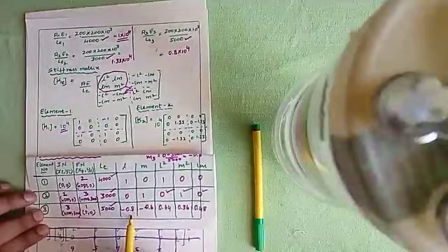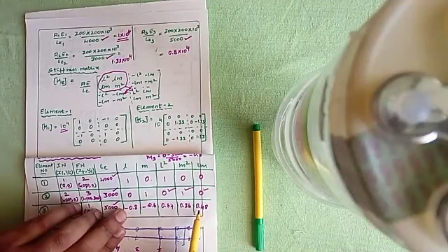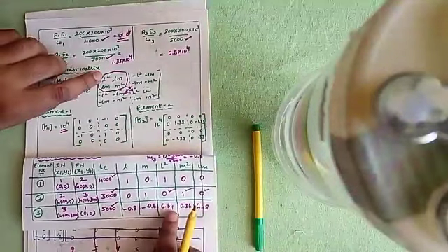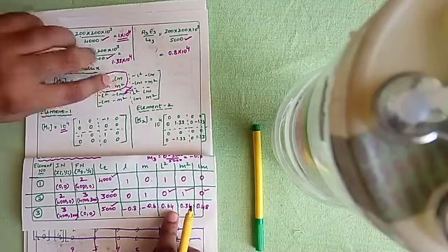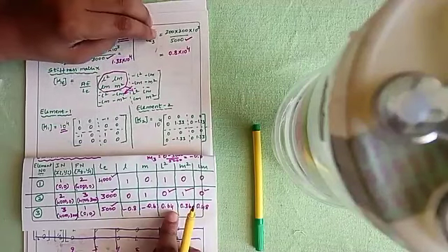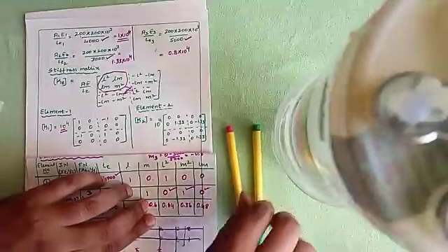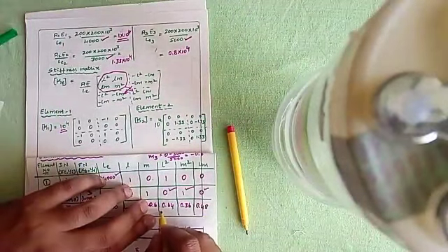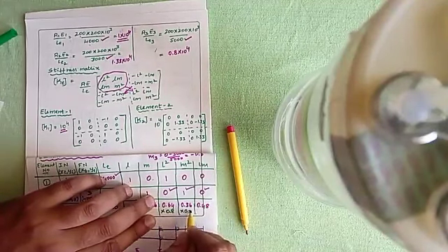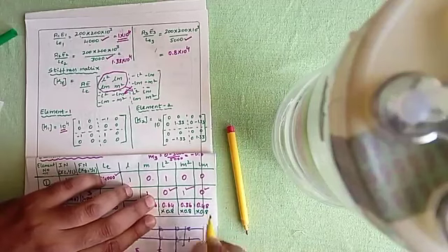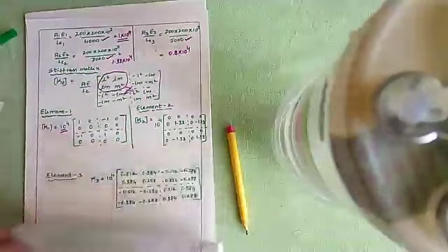Now let us come to element number 3. L² is 0.64, M² is 0.36, and LM is 0.48. So L² is 0.64, LM is 0.48, and here also you're going to get 0.48, and M² is 0.36. When you multiply A3E3/L3, you're going to get 0.8 × 10⁴. Now I'm going to multiply this L² with 0.8 inside the stiffness values, and 0.36 also with 0.8, and 0.48 also with 0.8, with 10⁴ kept common.